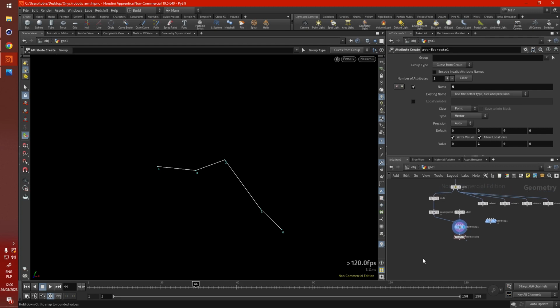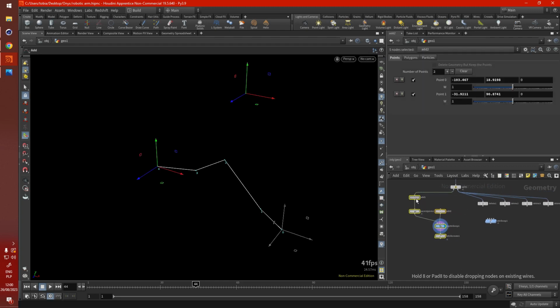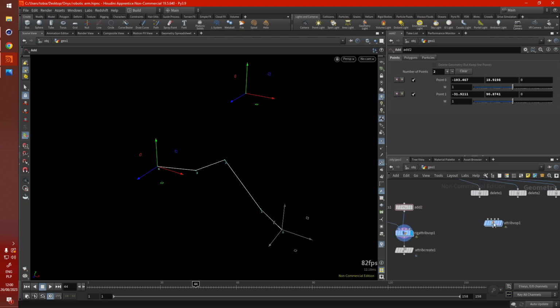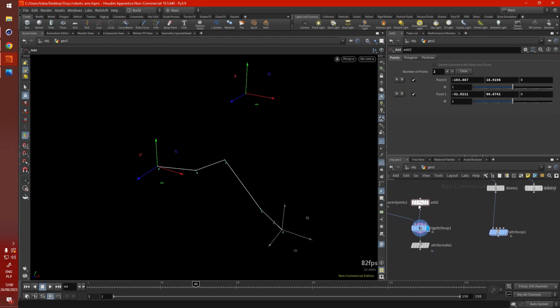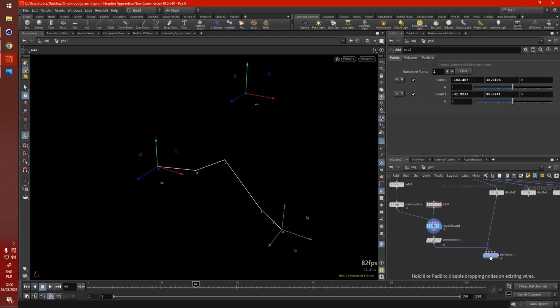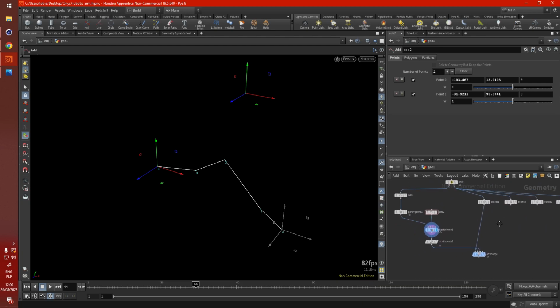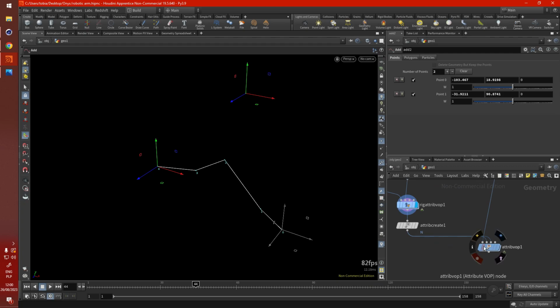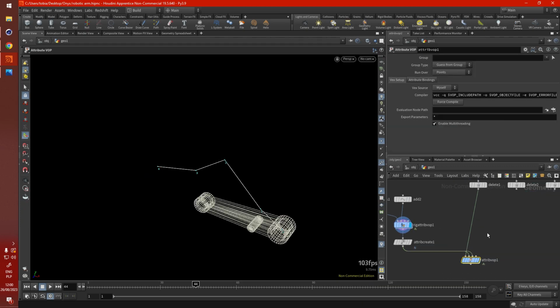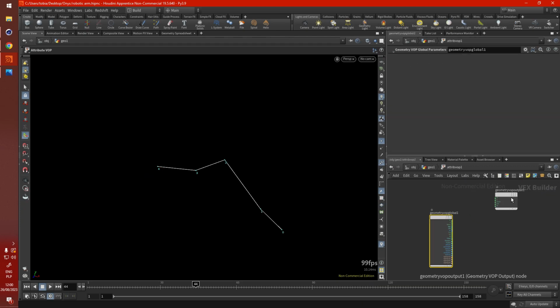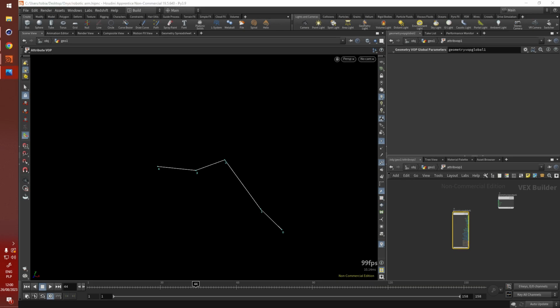So we've got our skeleton waiting here, it's all ready. Now we just have to do the matching process for the geometry. So bring that, connect that to that, and connect your skeleton to the second input and to the third input. This is just the way I've been doing it based off a different project I was working on. But because you're going to have to make this flexible for different parts, I'll show you how to create it with parameters, and you can recycle the same process over and over.